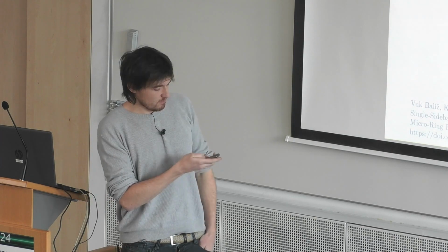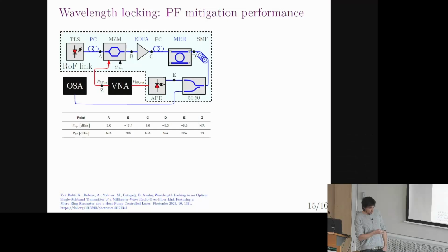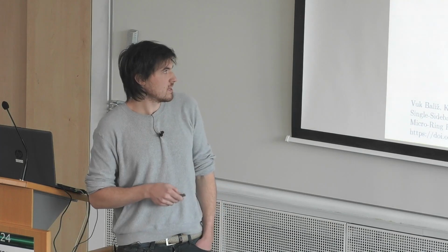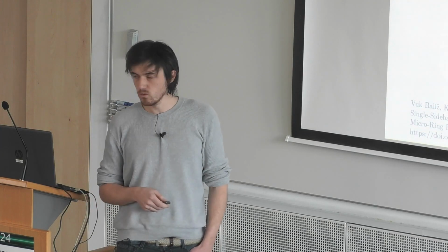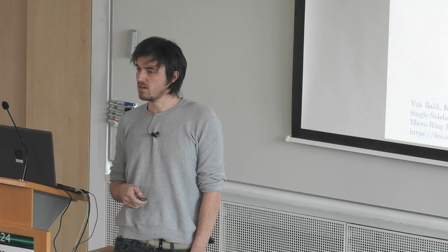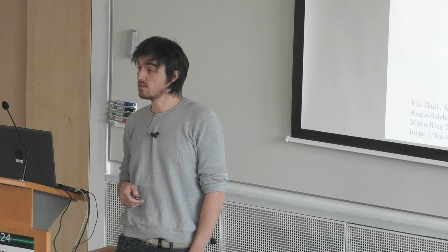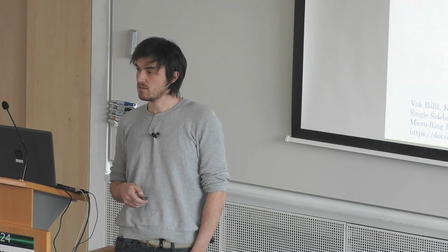That basically means that we unfortunately had to attenuate the signal by the non-ideal configuration of the Mach-Zehnder modulator, and then we brought that back by the EDFA. Other than that, we didn't really pay too much attention to the nonlinear effects.